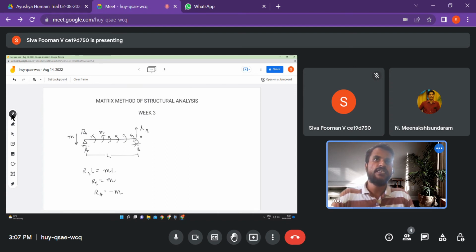Fine. So what will be the shear force then? Shear force diagram. It should be easy from this point, right? Shear force should be equal to m. Yes, it's a rectangle where I'll draw it here. Let's say this is the beam span. Okay, so this is the shear force diagram that I'm going to draw. So it'll be a rectangle, right? Because we have m and then it keeps constant and then it drops to 0 again, right? So this is the shear force diagram.